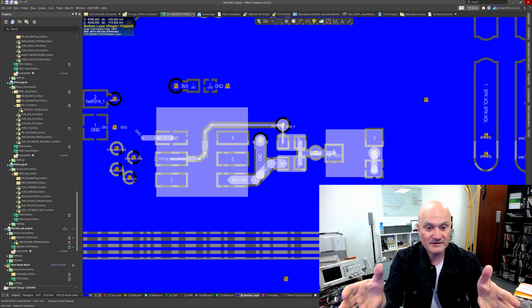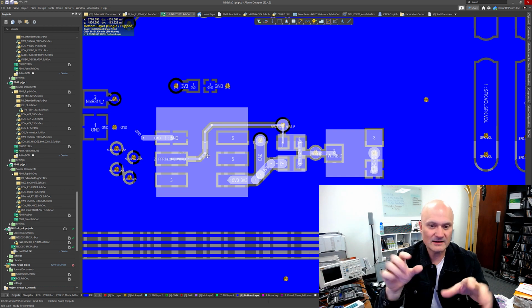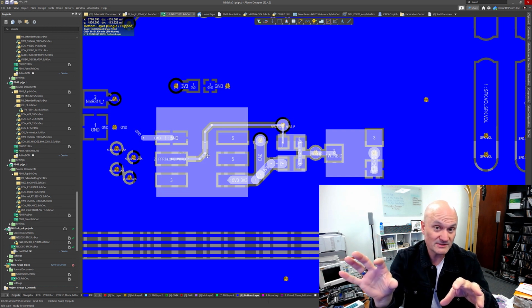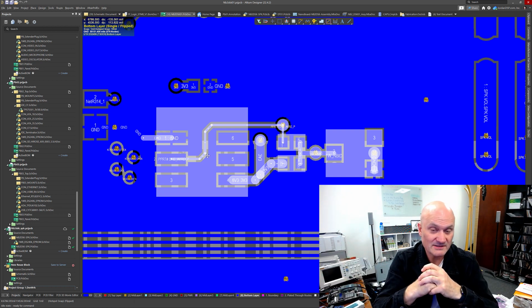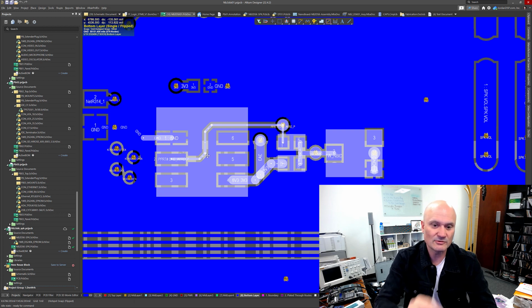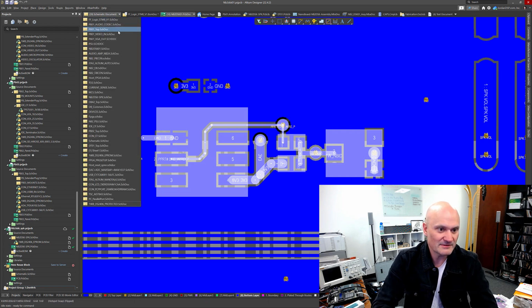So later on, normally when you use a snippet, you have to manually relink the components from the snippet from the board side to their counterparts in the schematic. And there are various scripts Altium users have shared in the community to automate some of that process, but you still got to jump through a few hoops. Nevertheless, that's the PCB side of the snippet.